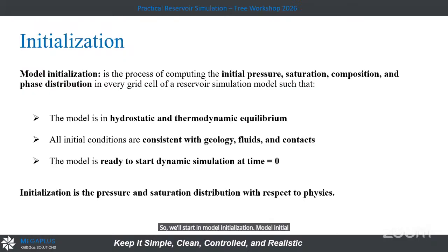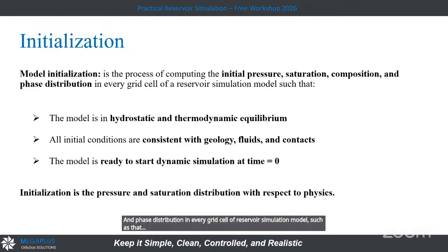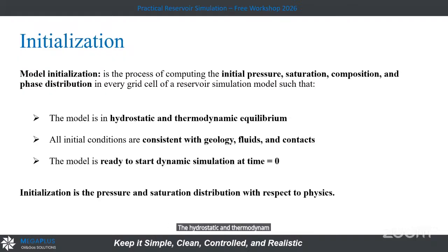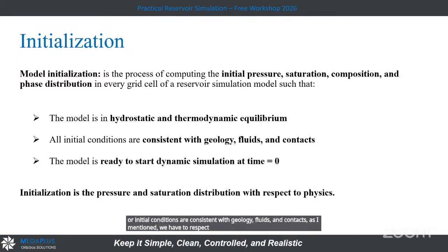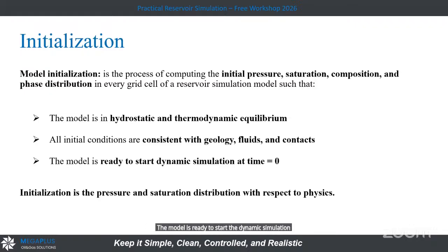Model initialization is the process of computing initial pressure, saturation, compositions, and phase distribution in every grid cell of the reservoir simulation model, such that under hydrostatic and thermodynamic equilibrium, which is the initialization by equilibrium, all initial conditions are consistent with geology, fluids, and contacts. As I mentioned, we have to respect the property and structure maps and faults, of course. The model is then ready to start the dynamic simulation at time zero, the initial condition. Its initialization comes from the state of the model at time zero.